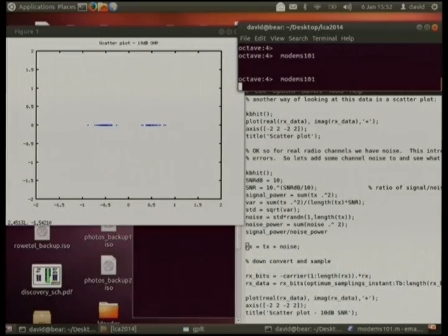Now this is a signal to noise ratio of 10 dB, which is round about the limits of analog communication if you're transmitting single sideband or voice. But you can still see, for digital, the 2 points in the scatter diagram are quite a long way away from this zero line down the centre. Now if enough noise was added to this side to move one of these points over to this side, you'd get a bit error. And likewise, if enough noise was added to a point that should be here to make it move over here, you'd get a bit error.